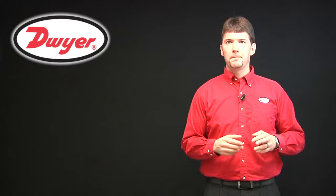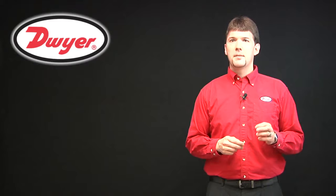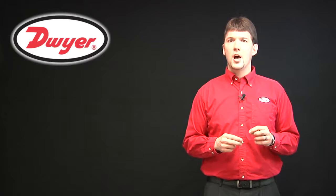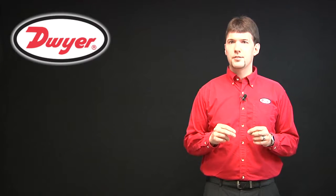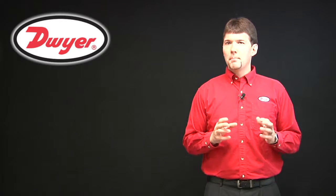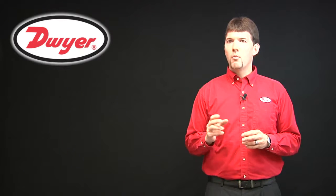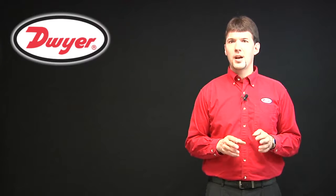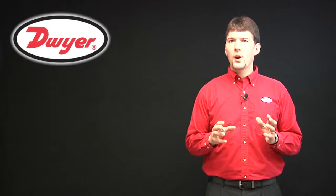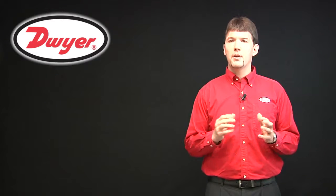So what is accuracy? The International Electrotechnical Commission, or IEC, defines accuracy as the positive and negative deviation from a curve observed in a testing device under specified conditions and procedures. Unfortunately, when it comes to defining accuracy for a pressure sensor, it's a bit more complicated. Accuracy has a large effect on the cost of the pressure sensor, or even more important, on the quality and efficiency of the process it measures. It's important to understand the factors determining accuracy and what questions to ask when selecting a sensor so that you can make a more informed decision when comparing pressure sensors.